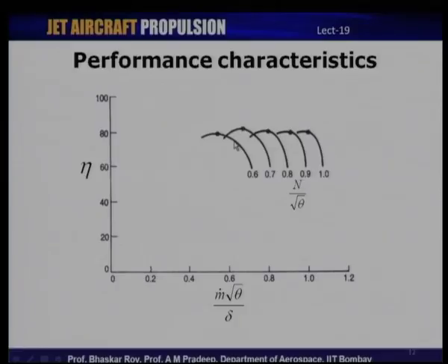So, what we have discussed so far are the performance characteristics of centrifugal compressors as well as the performance penalties which a compressor is likely to pay, especially as we change the operating range for a given speed. On one side it gets affected by surge, or even before that the compressor might enter into rotating stall, and also choking, which affects the performance on the other end.